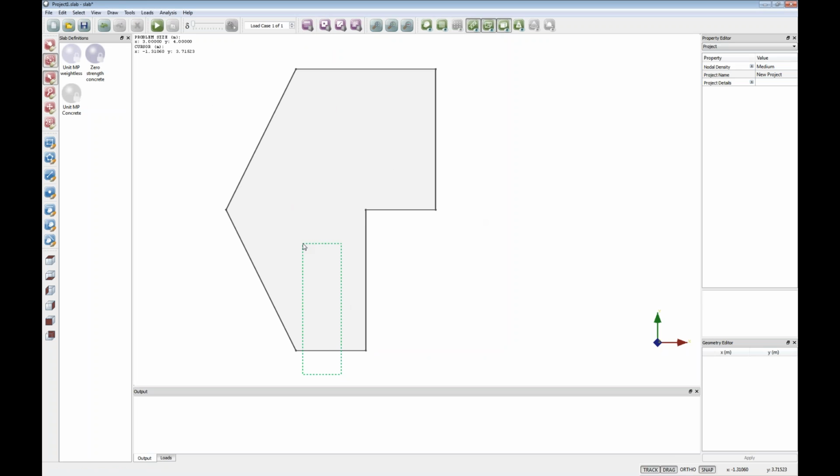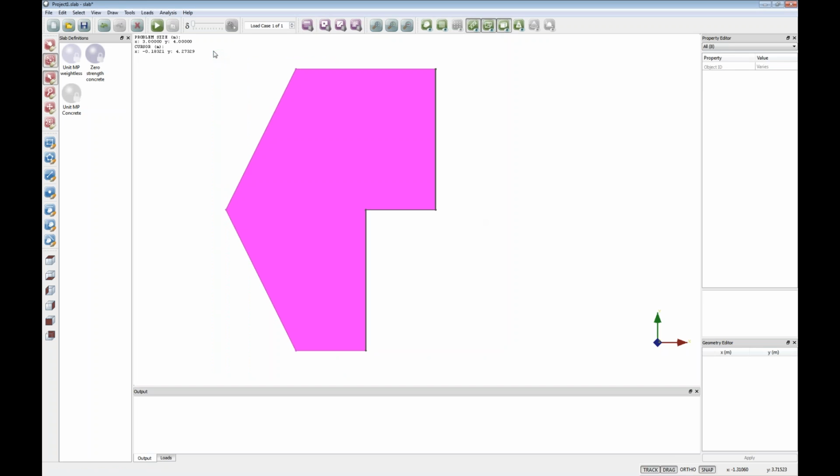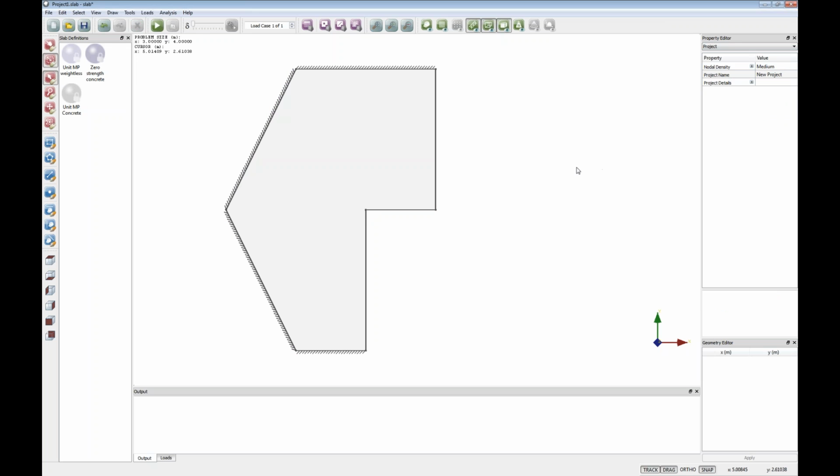actually define some of the supports to be simple. So I've got 1, 2, 3, 4 simple supports, and I've got 1, 2, 3 free edges. For now, I'm going to just apply a kind of dummy concrete slab property, so a slab property which has unit moment of resistance in each direction.